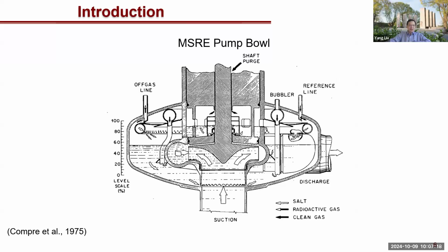Yeah, the bubbles generated in the molten salt reactor are through a different mechanism. You have the bubbler here, and you also have a molten salt jet. That jet impingement generates additional bubbles. Nobody has measured it, but previous research estimates the bubble size to be about 0.3, 0.4 millimeters. This was an estimate. So we are trying to recreate that bubble size using a different mechanism. Okay, that's what I was wondering.